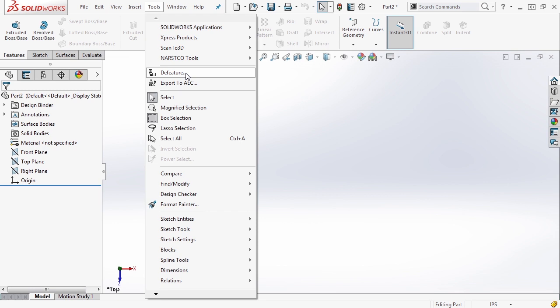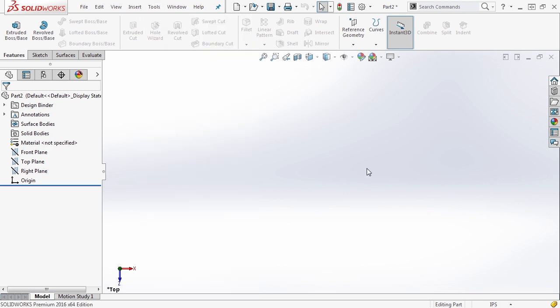All the information that you need, the mounting points, where your drive line is going to be, external splines for the drive shaft, and so on, without having to have all that internal detail and data in there. So Defeature, again, it's one of those tools that not a lot of people use or not a lot of people know it's there. But if you're exporting your data and you're trying to protect the proprietary internal data, or you're just trying to get a simplified model, check out Defeature. It can be pretty cool.